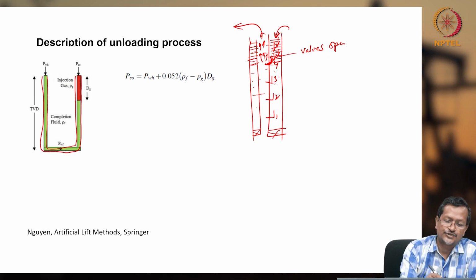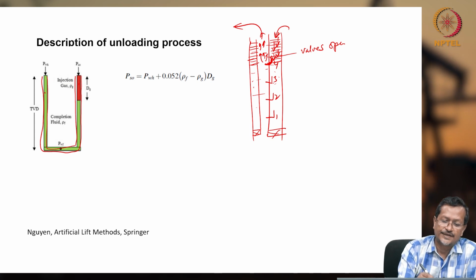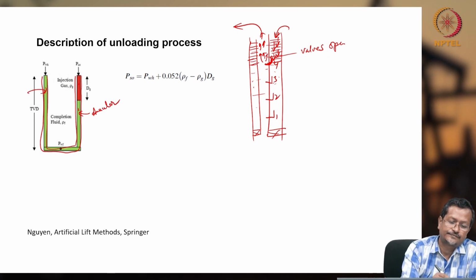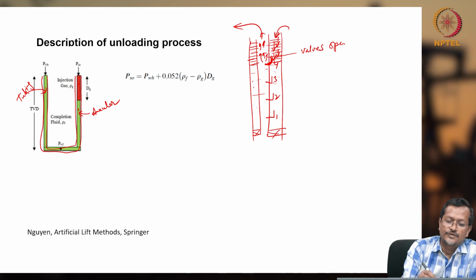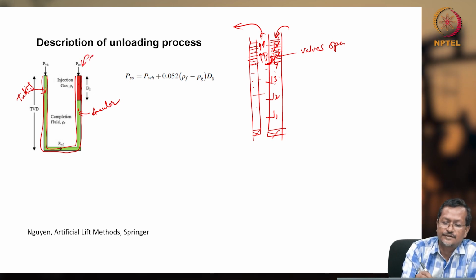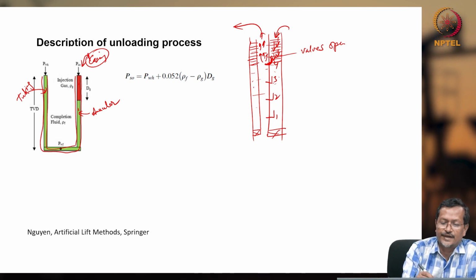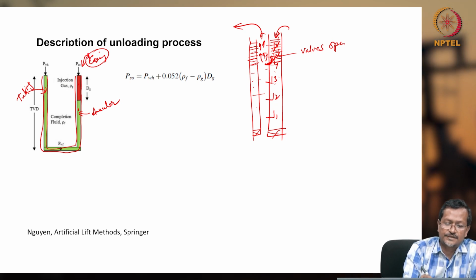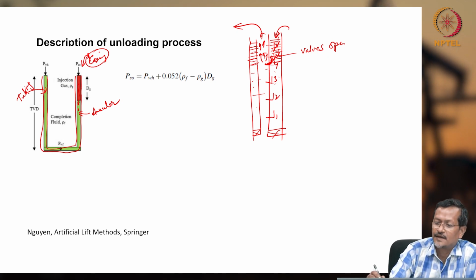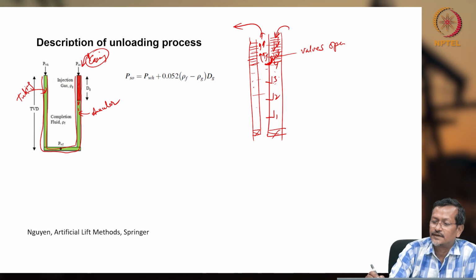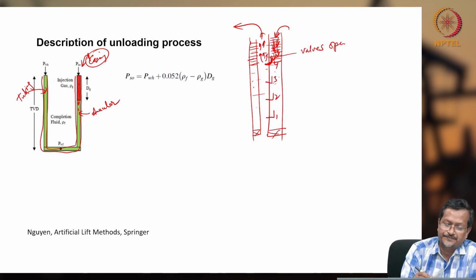I can assume this is tubing and this is annular area. This is the tubing area. So, you inject gas from here, the casing. Casing pressure will be there. You are injecting gas, and because of the gas, you are displacing this liquid by your gas only. Here also the same thing is happening. If you see this right side drawing, gas is replacing the liquid.